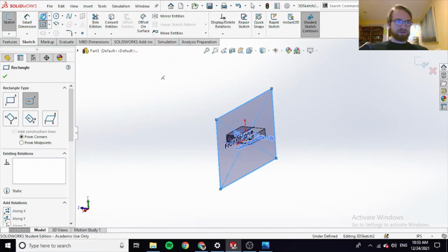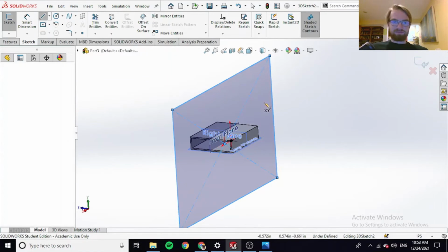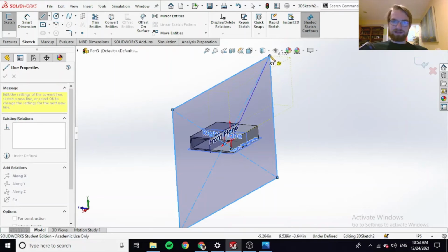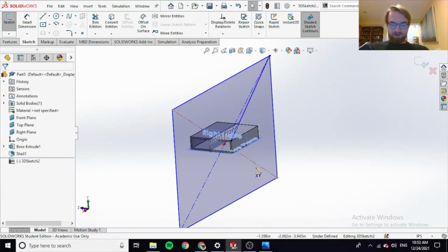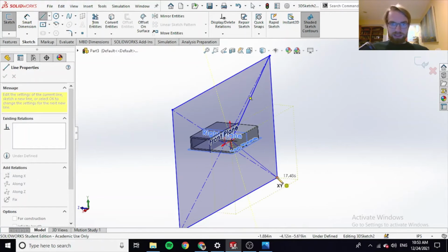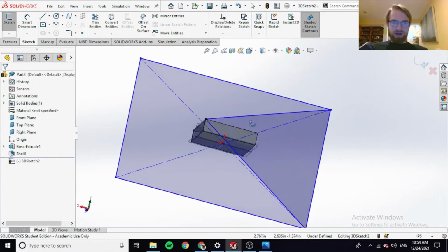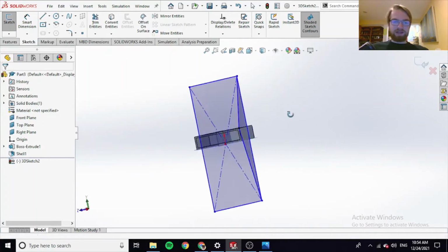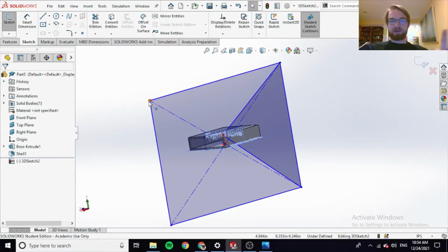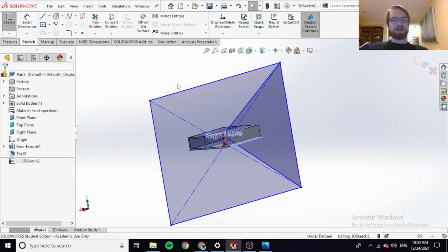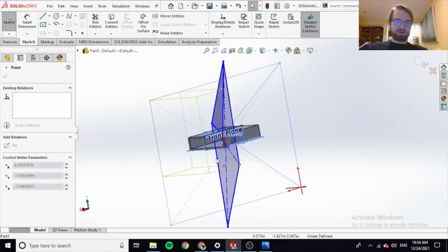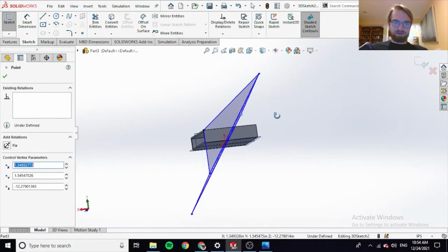Then you can also do stuff like maybe like this. And it's not important to follow along, guys, I'm just trying to demonstrate this. Alright, so now I have this other triangle that's totally out of plane with everything. So just be careful with 3D sketches. They can be constrained just like anything else, right? You can have relations, you can have constraints, but just be diligent with those constraints, because stuff can get really funky. Ooh, whoa, that's crazy.